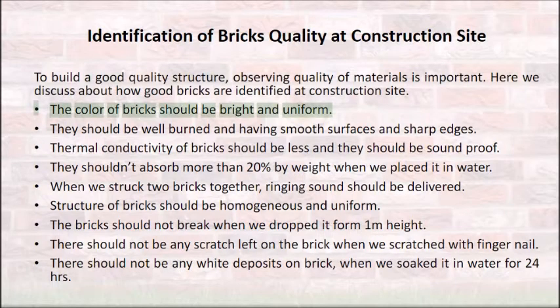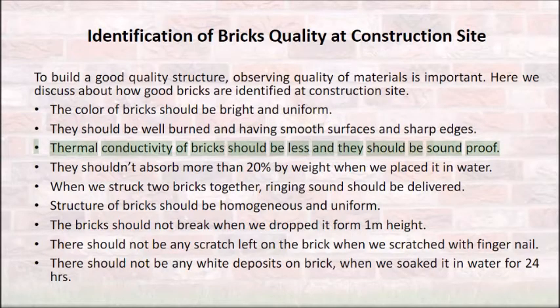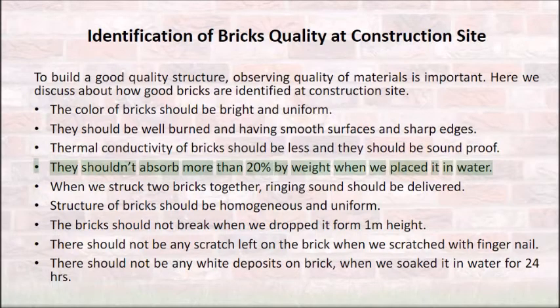The color of bricks should be bright and uniform. They should be well burned and have smooth surfaces and sharp edges. Thermal conductivity of bricks should be low and they should be soundproof. They shouldn't absorb more than 20% by weight when placed in water.